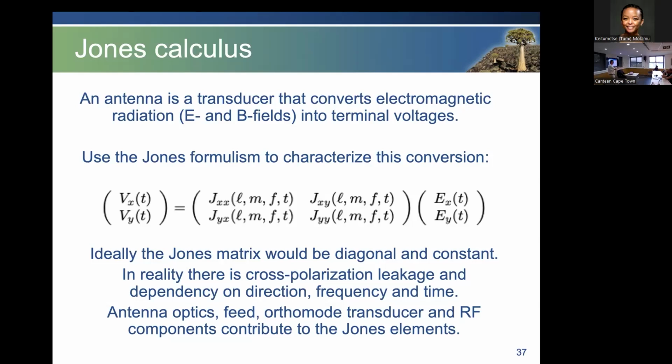But in order to do the maths more simply, you think about them as being analytic signals. And analytic signals are complex signals, where you take the real signal, you apply a Hilbert transformation to it, and then you make that the imaginary part of the signal. So there's no new information. All you've done is you've taken your signal and made it into a complex signal.